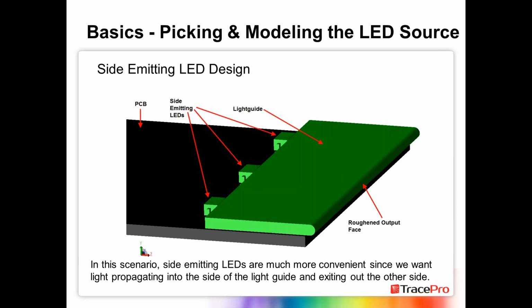And 3 LEDs work out really well for this type of setup, where each of them has a very bright LED emission in the center, and then they overlap with the second LED next to it in those areas between the LEDs. So that's this type of scenario here, and the side emitting LED makes it very convenient for light to go out that right-hand side and to create uniformity. So using the LED that fits the type of application can be advantageous.